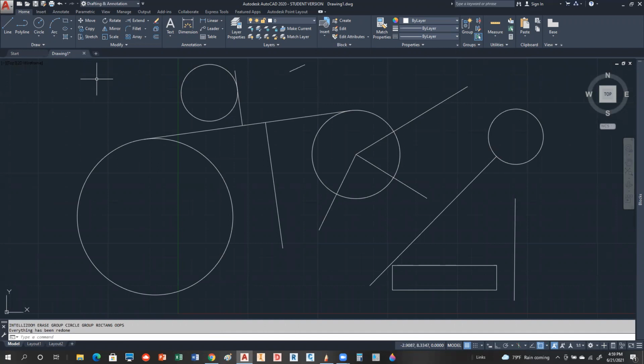Okay, so there's another option in undo called a mark. If I put a mark in here, I think of it like a dam, so it allows you to only go up to that point. So if I do an undo mark, now I can go out here and, let's say, I'm drawing a circle and a line.